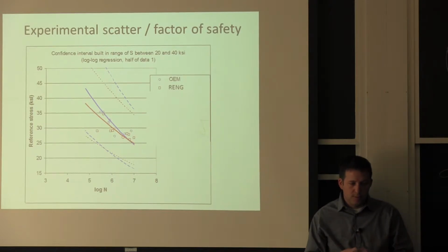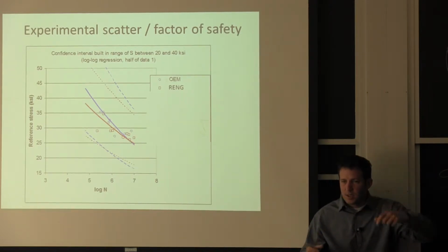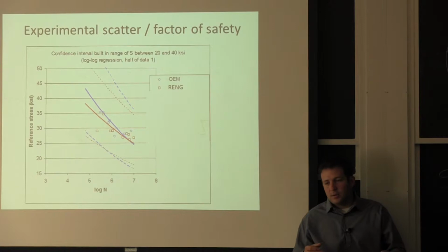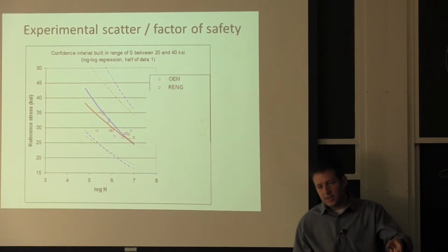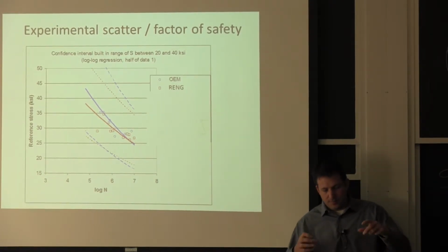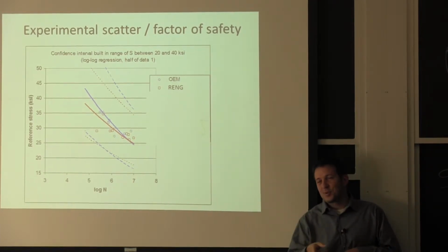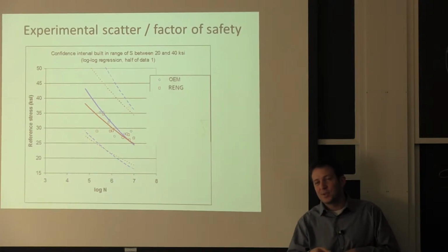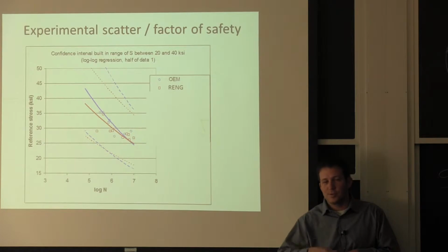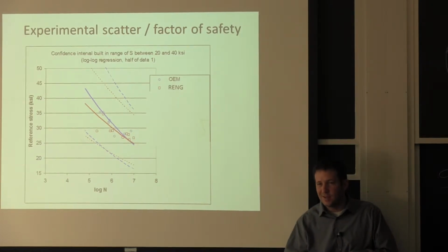These were just tensile specimens, and what I found from experience in running these high cycle fatigue tests is if in the whole section there's one particle that's larger, that's where the crack's going to end up. So it becomes a little bit more like a ceramic. On a ceramic, that's very notorious. You're looking at the largest porosity, that's where the crack's going to start. Doesn't matter if you have 1,000 of them, you only need one in one area.